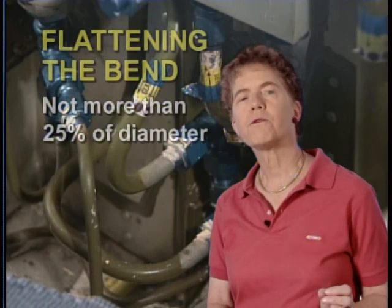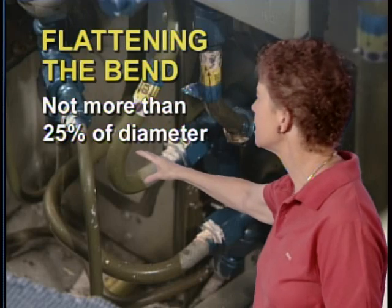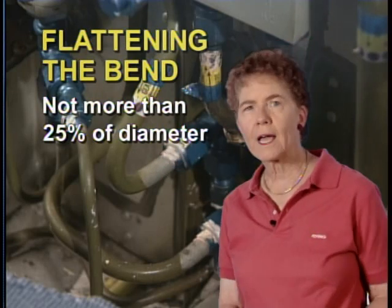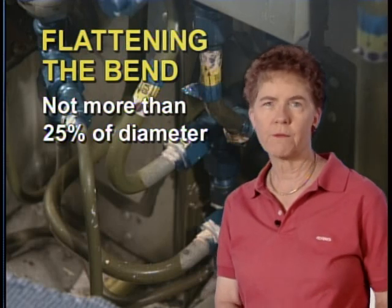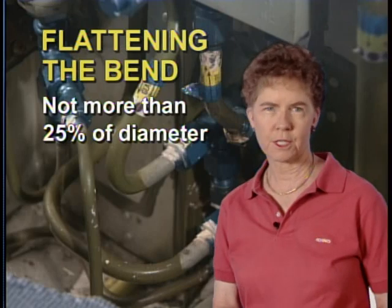Kinks, wrinkles, and excessive flattening, reducing the tube diameter, are not acceptable. When you make a bend in a tube, the flattening of the bend cannot be more than 25% of the original diameter of the tube. So flattening by not more than 25% of the original tube diameter is permissible.